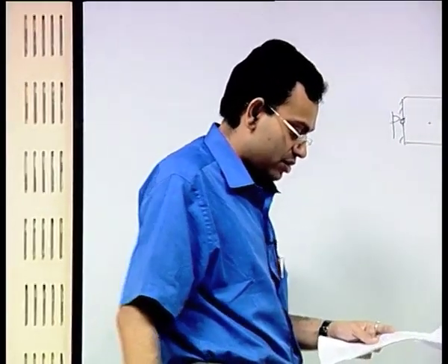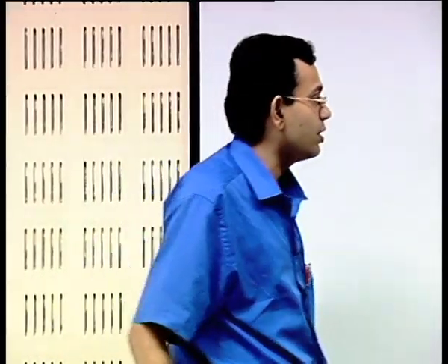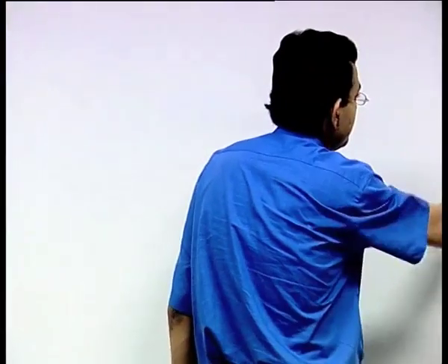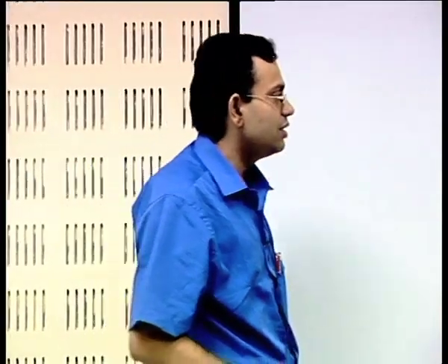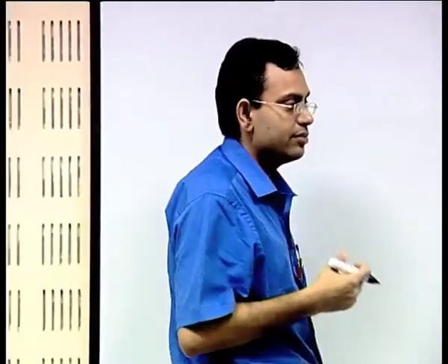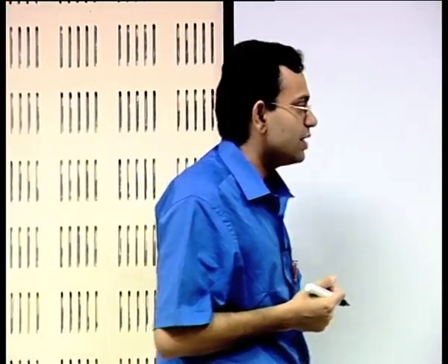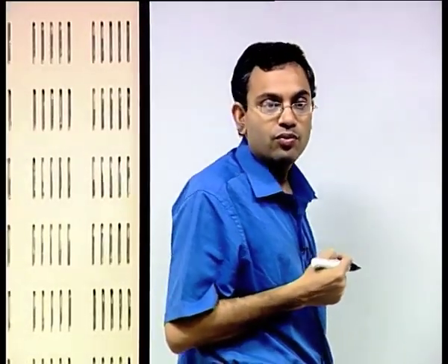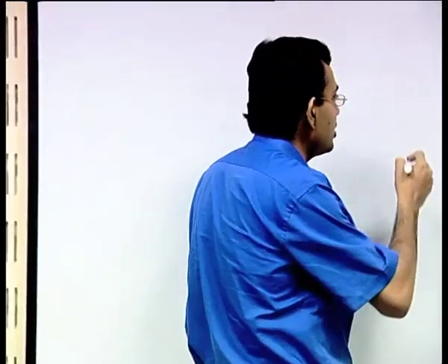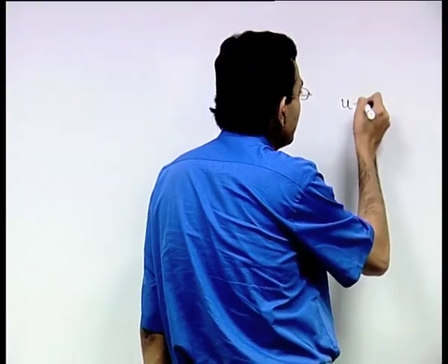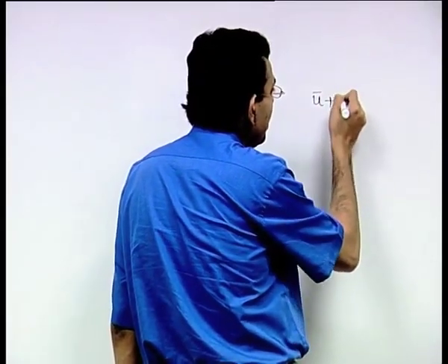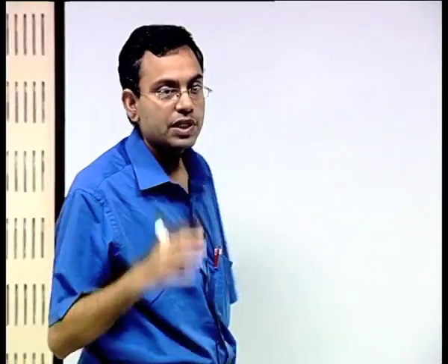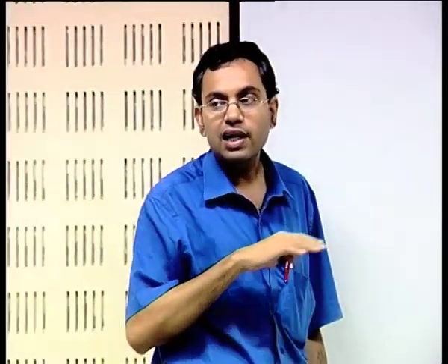Next question, what is closure problem in turbulence modeling? So this also we have discussed, but let us again summarize that in turbulence modeling we come up with the Reynolds average Navier-Stokes equations, where we basically decompose all the quantities, say the velocity, in terms of the mean and its fluctuation, substitute that in the Navier-Stokes equation and take the average.